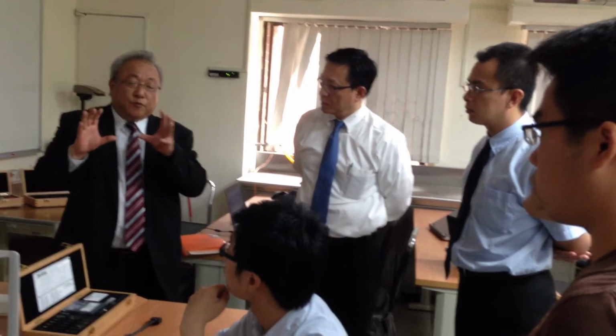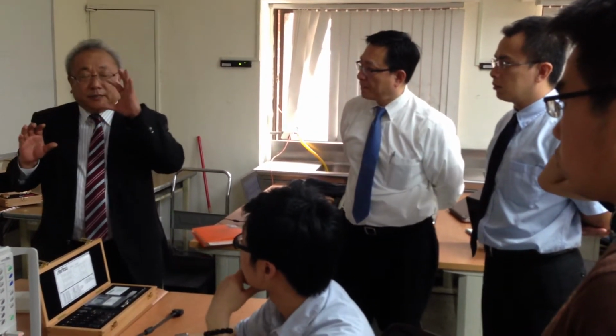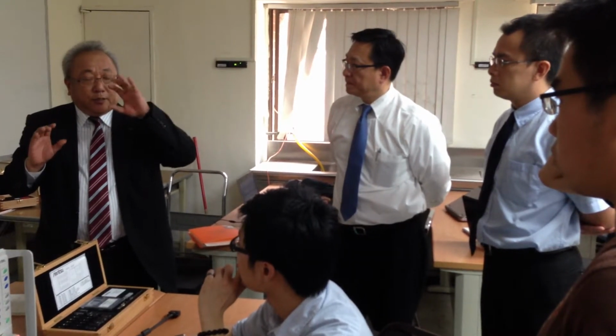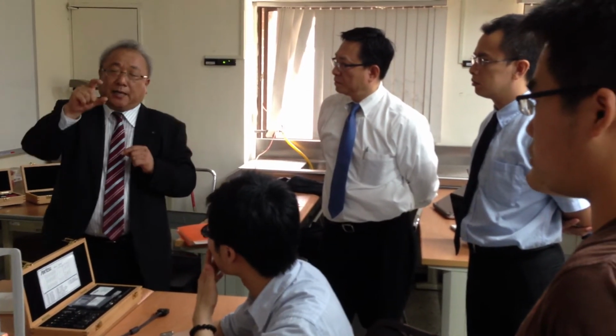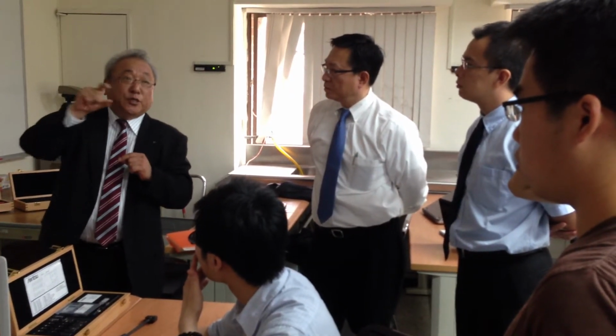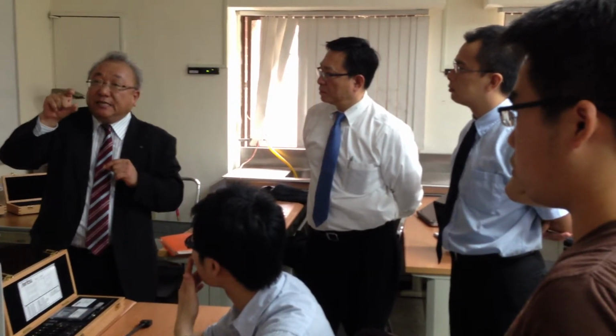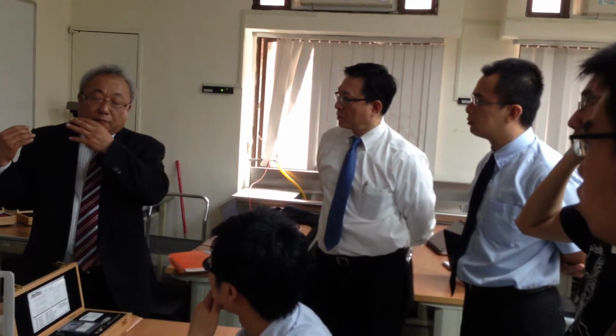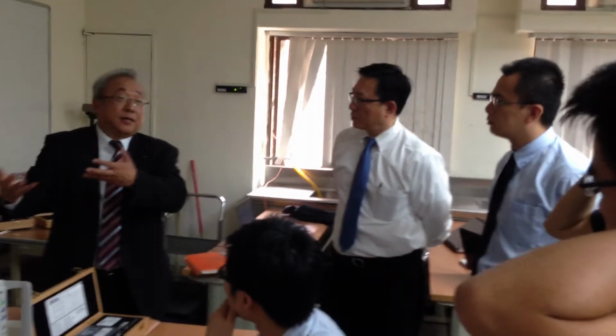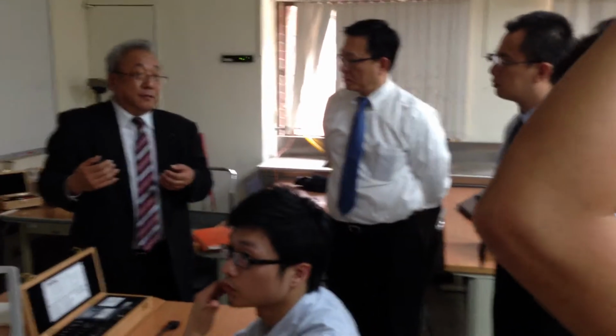And also, if you already have an uncertainty window, like plus minus 0.3 dB for the noise figure measurement, you can set this kind of limit first, then calculate the required composite receiver gain or something like that.